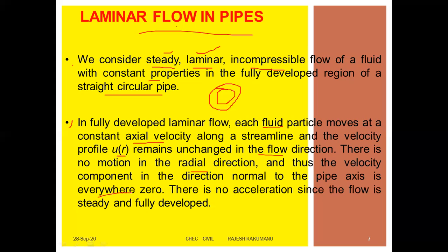There is no acceleration since the flow is steady and fully developed. Why? Because the flow is steady, laminar, incompressible and fully developed.